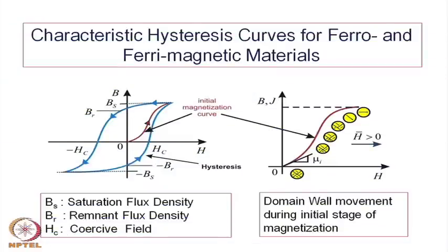This was already shown and presented. So, we have a hysteresis loop both in ferrimagnetic as well as ferromagnetic materials, and the basic reason is that we have a spontaneous polarization both in ferromagnetic and ferrimagnetic ordering. In the absence of any external magnetic field H, the magnetic induction or polarization is 0, and as we increase the magnetic field, it increases non-linearly with increasing field.